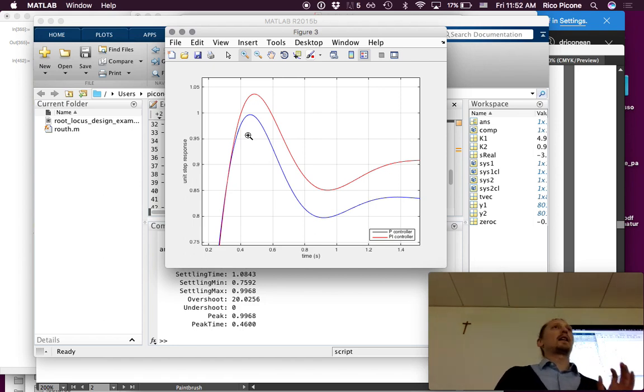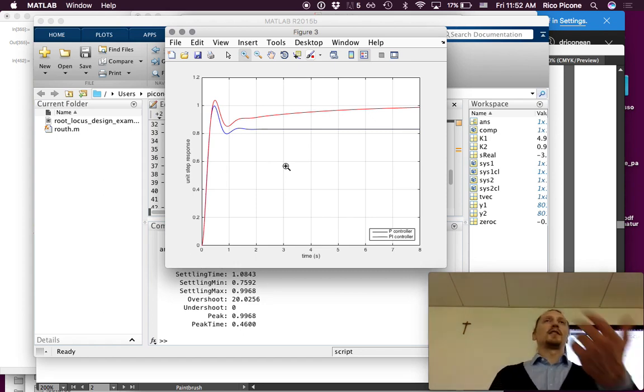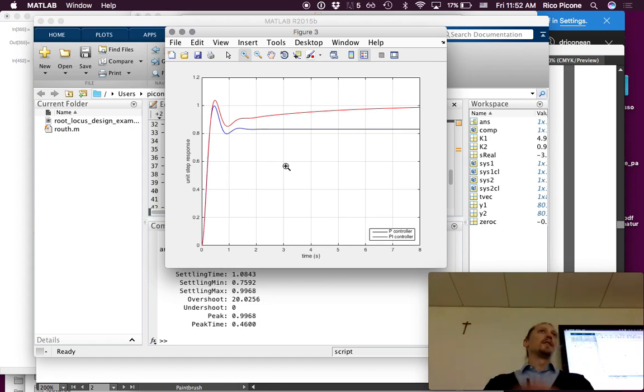So we could go back and sacrifice more settling time, and we could improve this steady state compensation to make it faster. So it's sort of a trade-off, and I think that, in my opinion, I would probably go a little bit more left with that 0, so that we could get a little bit faster steady state error compensation. That would just be my personal preference. It kind of depends on the system that you're going for, though. I like to see it respond a little bit faster.